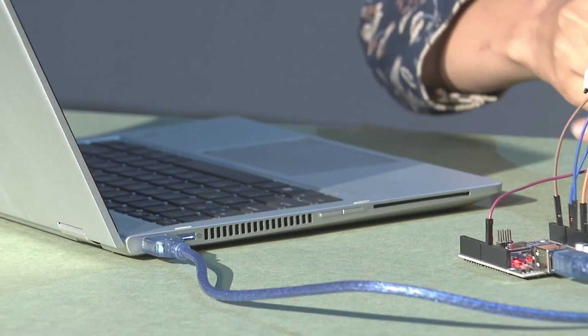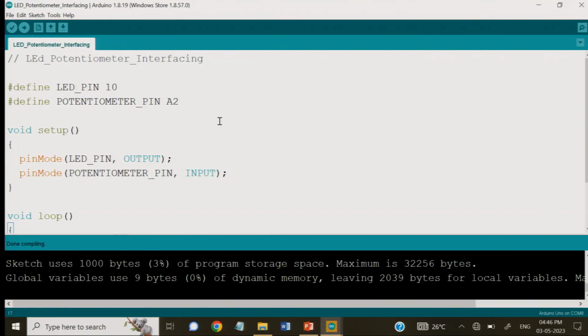So, first of all, as we know, we have to connect your USB terminal, and we will be inserting it into the USB port of your system. After that, we have to compile and upload your code, but of course, before that we need to select the port, as well as verify if the board is selected accurately.